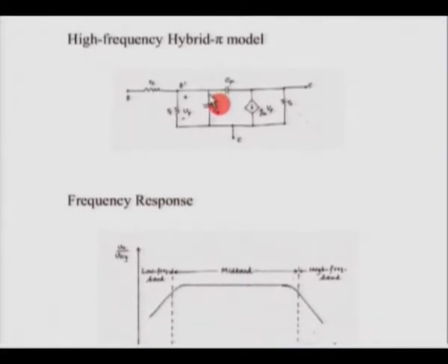Now here we would see that when we do the analysis, we know that the collector terminal, we did earlier, also from an analysis we saw that in a common emitter amplifier the output terminal is minus Gm times Rc parallel RL times the input voltage, say in this case V pi.